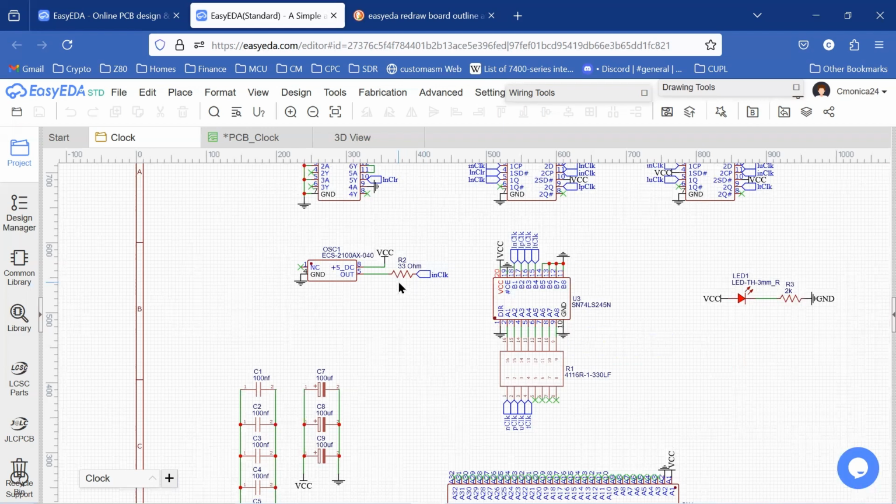So what happens is when we have the signal traveling down the trace, it reaches the end of the trace. Some portion of that signal reflects back down the trace again. And these 33 ohm resistors help to dissipate those bounce back signals. So we use those mostly going to the backplane, and that's what this is here, a 33 ohm resistor network going to the backplane.